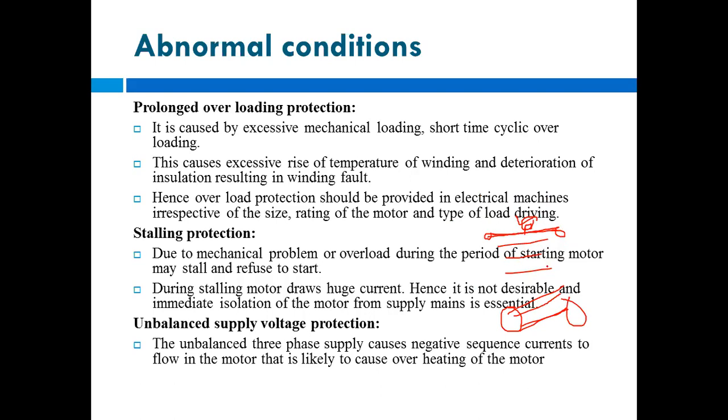Your motor will refuse to start. So here the stalling protection means that due to a mechanical problem or overload during the period of starting, the motor may stall and refuse to start.